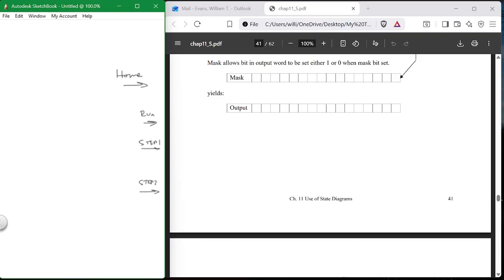So again, some people say sequencers are the answer. And other people say, I'll never use a sequencer because they're hard to troubleshoot. You have these two dichotomies, and some people like them, some people don't. I personally do not care for sequencer instructions. And if you follow the two main players, Siemens and Allen Bradley has it because they're mimicking the drum sequencer, the drum circuit. Siemens doesn't even have the instruction in their instruction list.